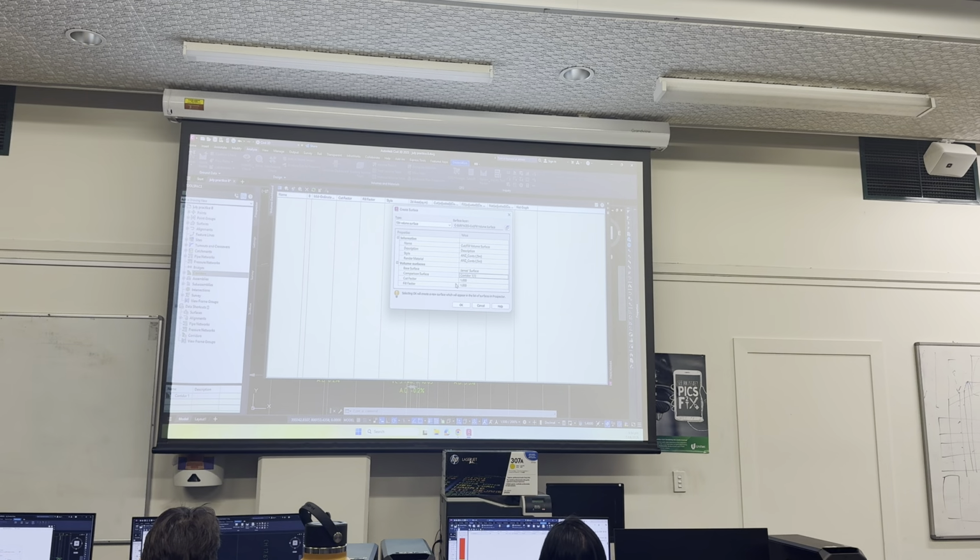If we take out some cut, we fill it, it's 1 to 3. But for the purpose of this course, we will just leave it as 1 to 1. Just in the future, if you're working with Civil 3D roading, you have to change these, because cut and fill is not 1 to 1. But for the purpose of this course, we'll just leave it.